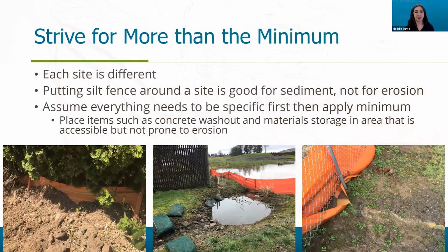So you should strive for more than the minimum. Putting silt fence around every single site is not the catch-all for erosion and sediment control. Every site is different, and putting a silt fence around the site is good for sediment and it is good for containing the site. It doesn't always handle erosion, so you should always assume that all your BMPs need to be site-specific and then apply the minimum.